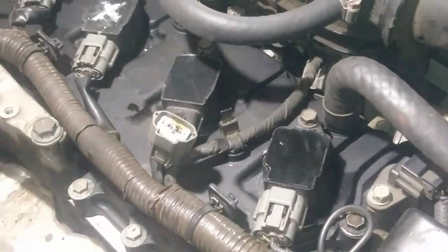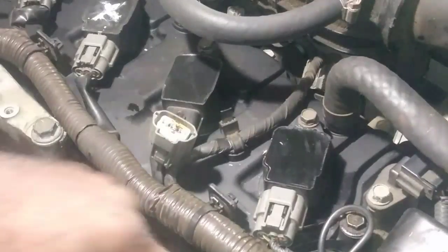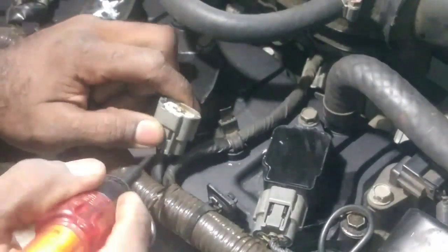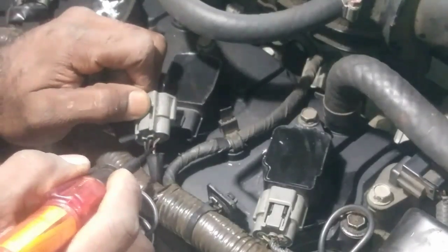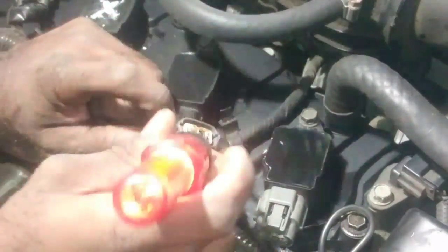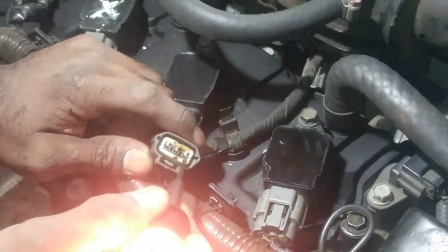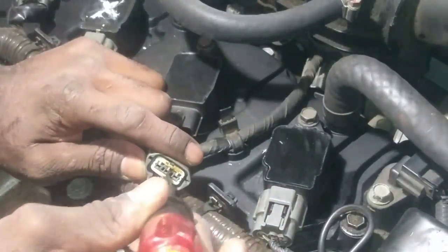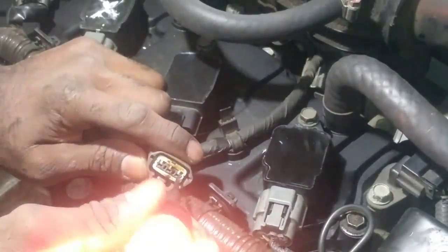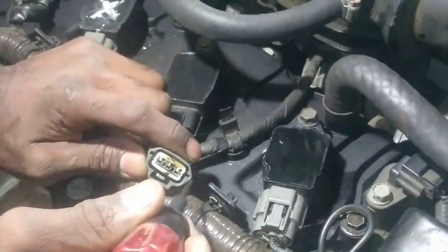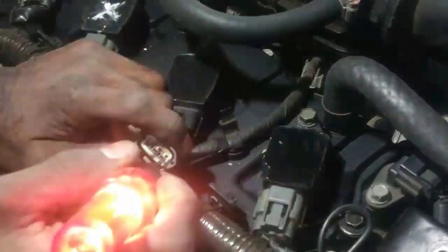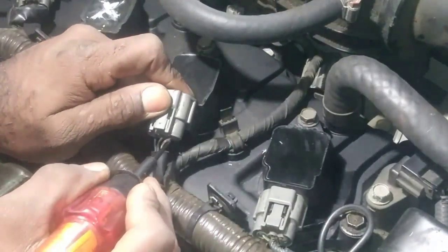It'll be easier, let me ground it right here. So we're grounded here on the cylinder head. We're going to look for 12 volts, and 12 volts is typically going to be a red color. Again, this is 3-wire. Here's my 12 volts. All the other ones don't illuminate. We're connecting the circuit, shorting this light out, and it's producing 12 volts and grounding right here. So here we have our 12 volt side.